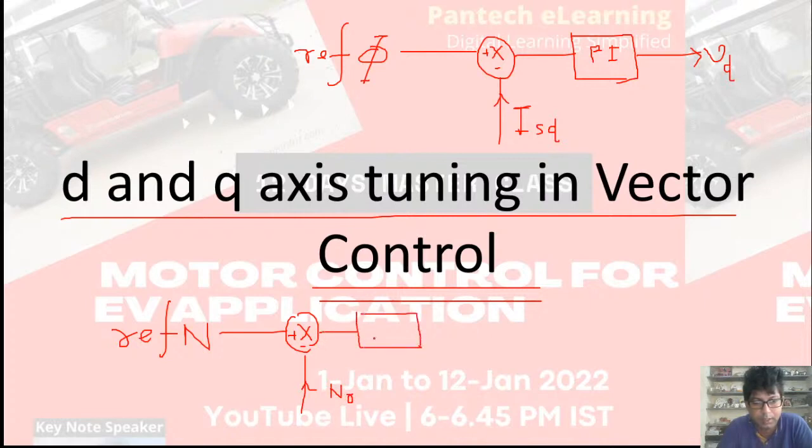Then there is a PI regulator. This is generating the torque reference. You know, the torque producing component is nothing but the armature current component, which is nothing but the quadrature axis component. Then this is again going to one comparator.